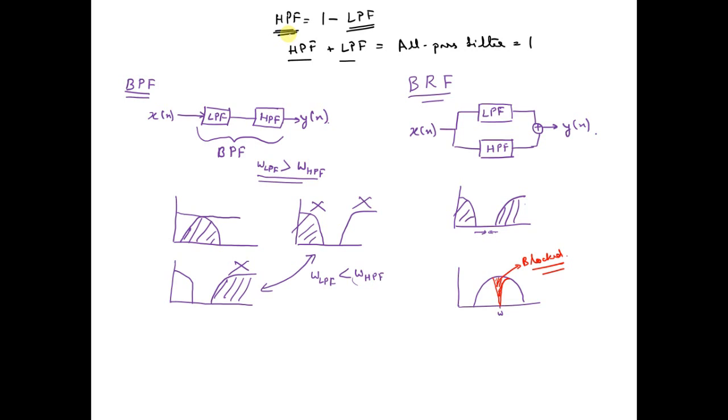Now we have the band pass filter. Another important thing you should keep in mind is that for this equation to be valid, you should have the same cutoff frequency for both of the filters. Both of them should have the same cutoff frequency.